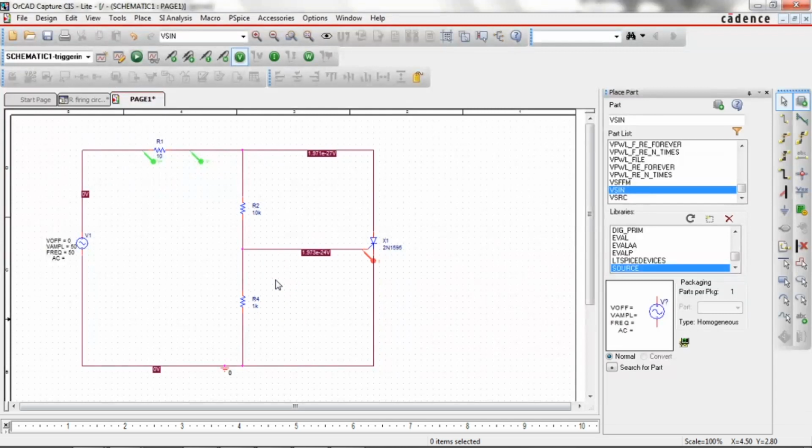It means after the zero crossover till 5 milliseconds, the current given to the gate terminal should not reach 1.9 milliamps. Only at 5 milliseconds should the current flowing towards the gate equal 1.9 milliamps. Okay, what to do now? Shall I increase the current or decrease the current? Because the voltage developed is the product of current and resistance. When sufficient voltage is generated here, only then does sufficient current flow here.